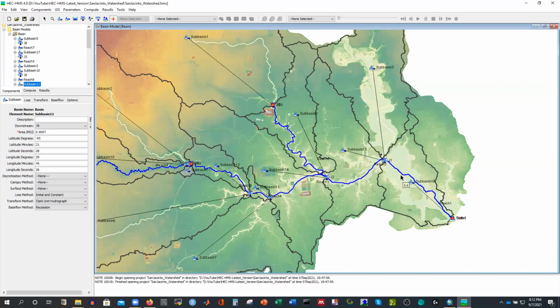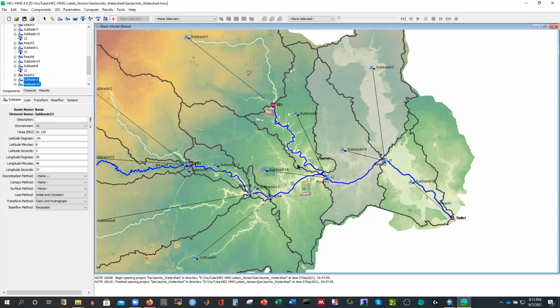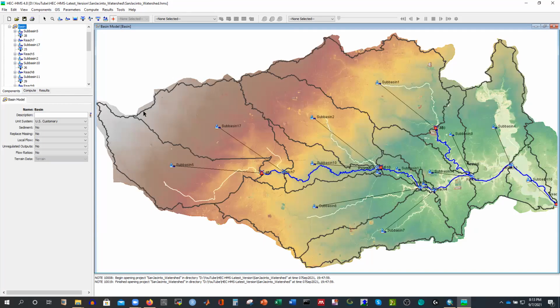We have one from here, so we can even merge this together because we have the common outlet, this one and that one, right? These are even draining to that point. So even if you calculate it separately, we have to sum them up to get the accurate value. So I'm going to merge them together so that our calculation will be simple.